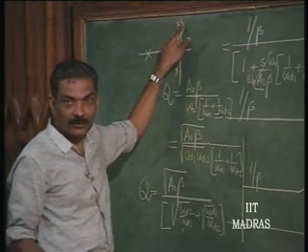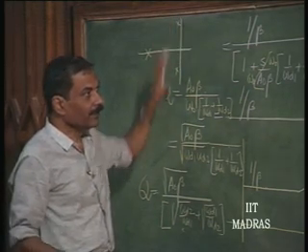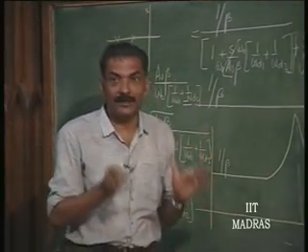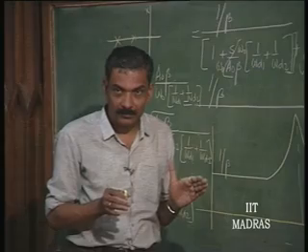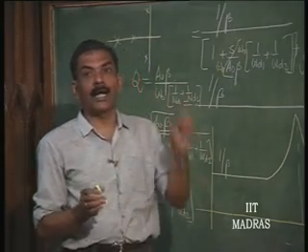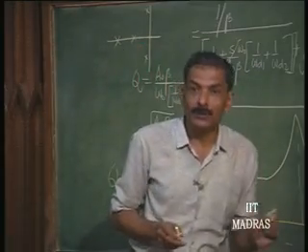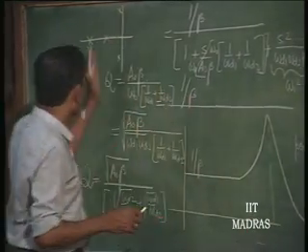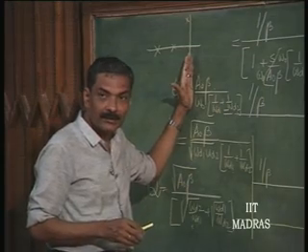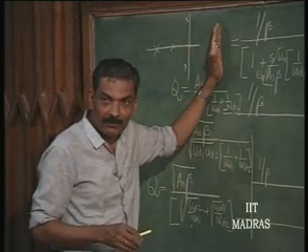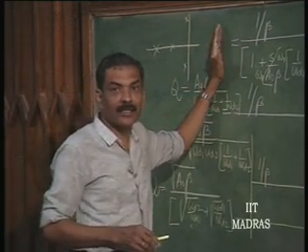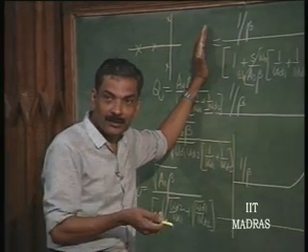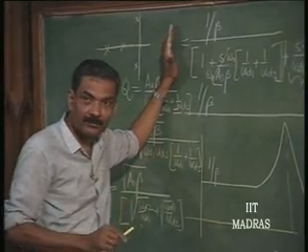Right. So, this is the problem, that a negative feedback system is stable as long as the order of the system is second order. More than second order, it can become unstable. The poles can lie on the imaginary axis, or they can lie on the positive half of the S plane. That means, it can become unstable. It will start oscillating at the natural frequency of the system, which is omega naught. Right.